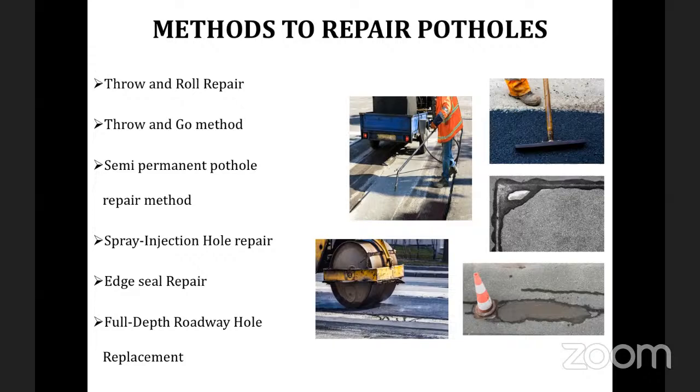In the throw and go method, the material will be shoveled into an unprepared pothole, which may contain water or debris. We have to see that the water and debris are not there. And once with the shovel they compact it, the next compaction will be left to the traffic. So that is the throw and go method.